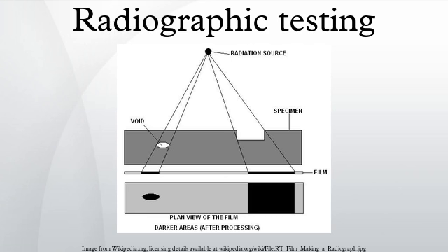Since the amount of radiation emerging from the opposite side of the material can be detected and measured, variations in this amount of radiation are used to determine thickness or composition of material. Penetrating radiations are those restricted to that part of the electromagnetic spectrum of wavelength less than about 10 nanometers.